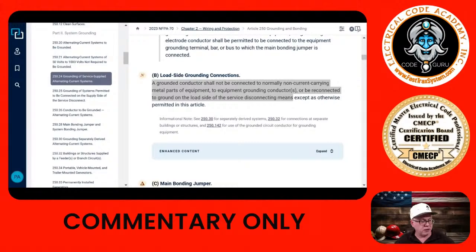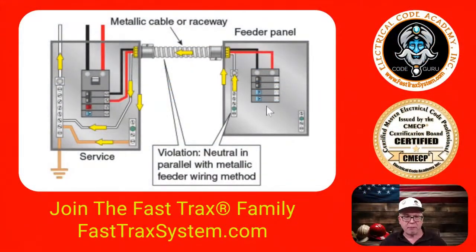So in our case, this is what's taking place. Some people say, well, Paul, just remove this screw, and now this bus is isolated. Well, first of all, we don't know that it's isolated because it could be screwed straight to the metal enclosure, even though they did put the green screw in there. So it needs to be floating, not in contact with the metal, okay? And you see this bus over here, which does have the green screw. This is fine because that connects this bus to this enclosure. And ideally, if this was MC cable, for example, then we would have an equipment ground run with it, running over here to here, and then we would isolate this neutral by taking this green screw out, and we'd be done.